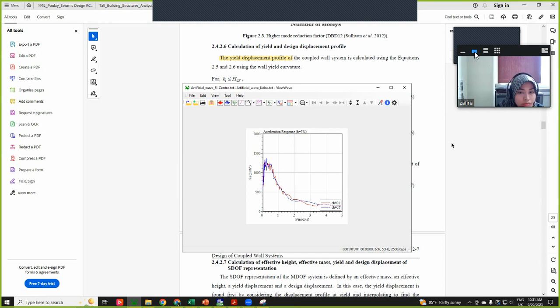But the estimation by displacement-based design, the blue straight line, changes, right? Yes, depending on the capacity of the damper. And you try to get the convergence point. So this is a design procedure. So you must do it first. Then after you get the convergence, you go to time history analysis.